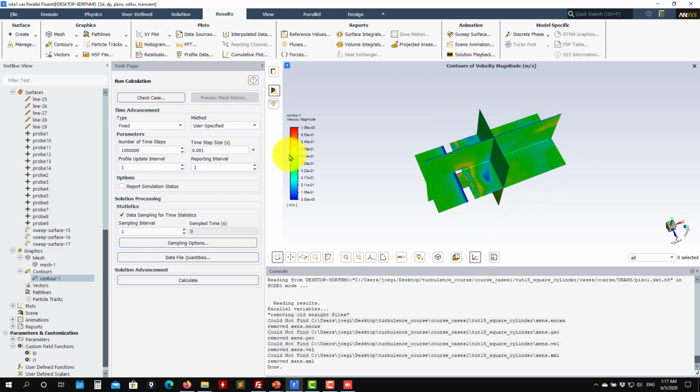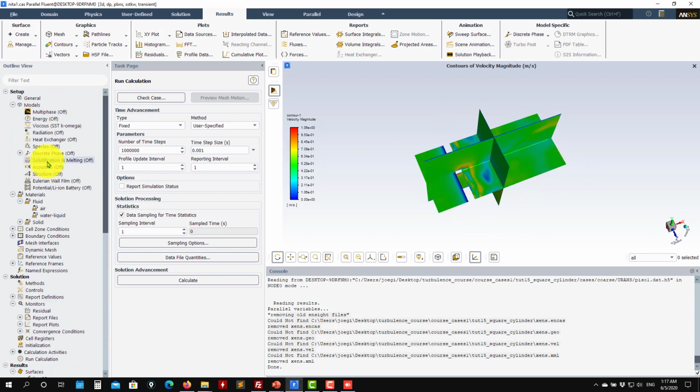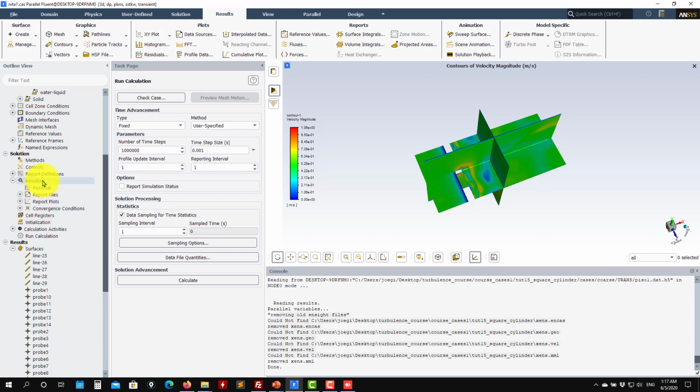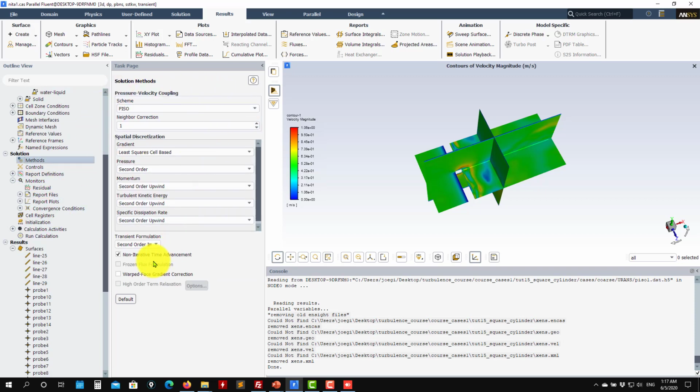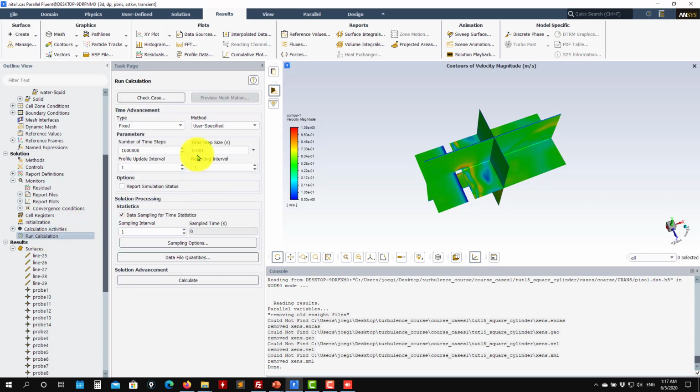So we're going to use the NITA, starting down in the PISO. Remember that in NITA, you go here, non-iterative, then PISO, you have 2 options. You can play around with bias, but for instance, use the PISO one. The idea of NITA is that you see here you have the inner iteration, and it's not doing those iterations.